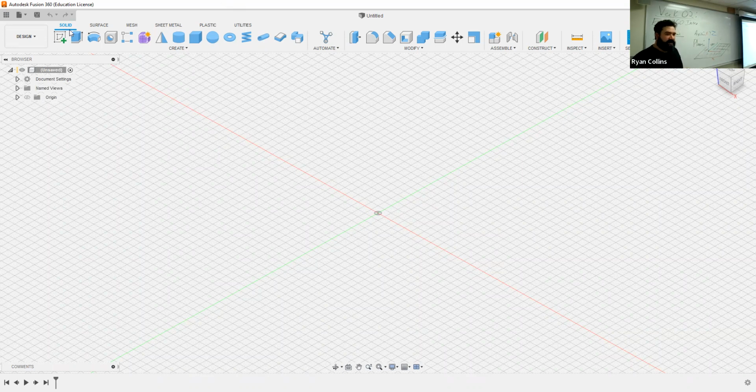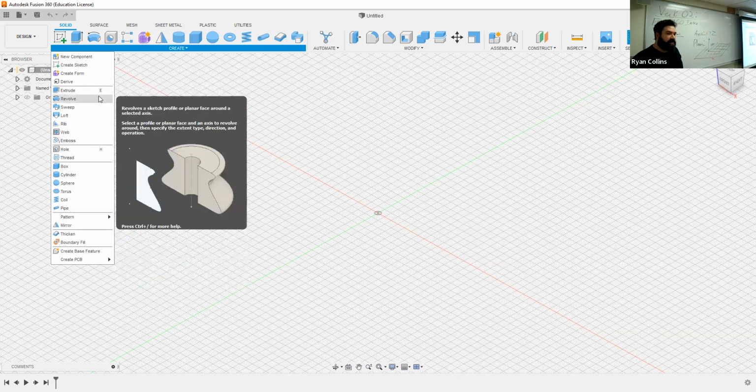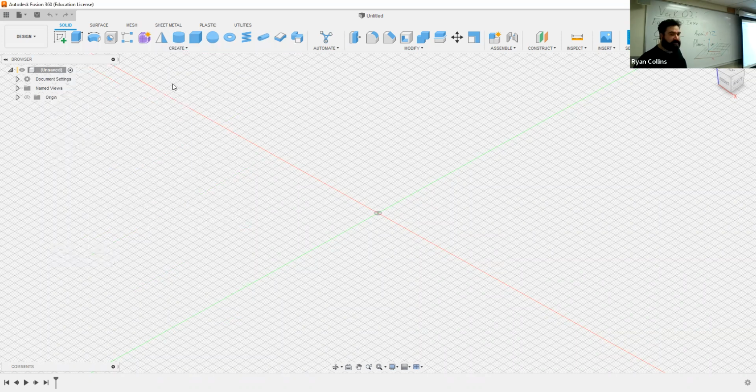So if you're working on solids, here's all your predetermined solids. Like I said, with object-based modeling, you have a drop-down as well of a bunch of different ones, and you'll see some pre-assigned hotkeys. If you mouse over any of these, you see this vertical ellipses, these 3 dots. You can right-click on that and add it both to the toolbar and your shortcuts. I'll show you how to find the shortcuts in a moment. Actually, you just press S, shortcuts. It'll bring up a search tool.